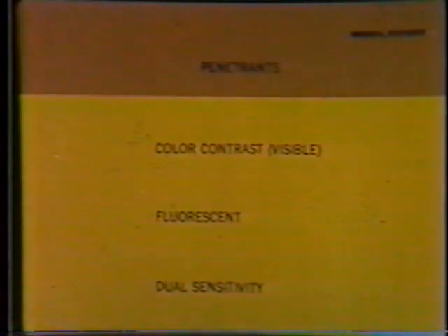Different liquid penetrant processes are identified by the type penetrant used. The most versatile but least sensitive are the color contrast or visible dye penetrants. The dye, usually a bright red, is sometimes a special color, such as blue. The chief limitation is a marginal ability to provide enough contrast to detect fine openings.